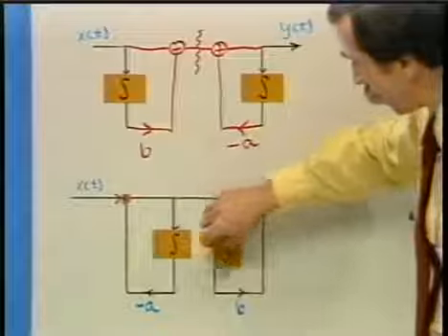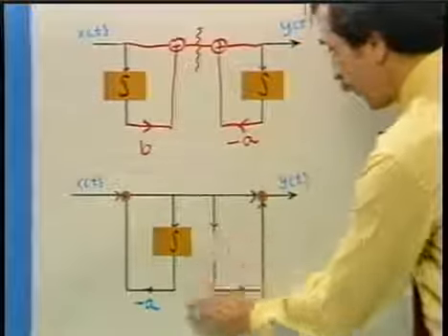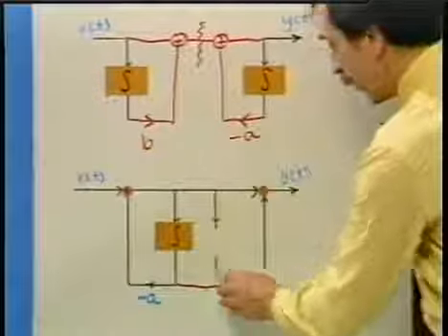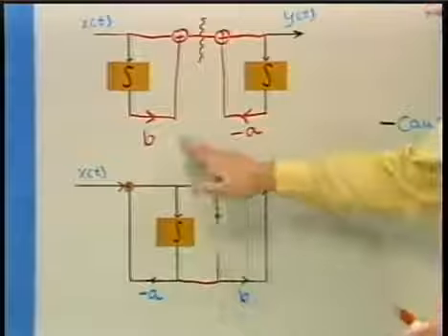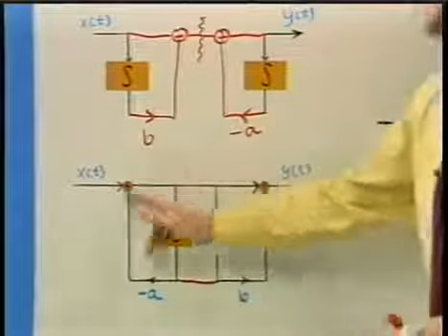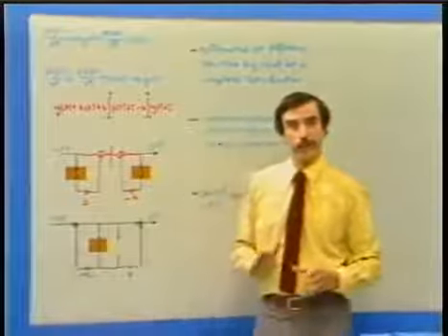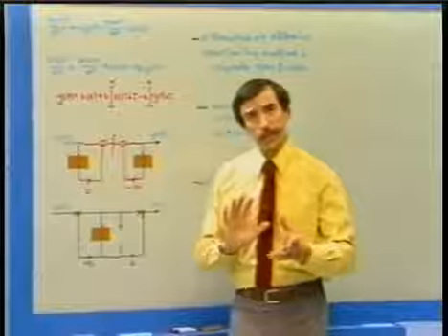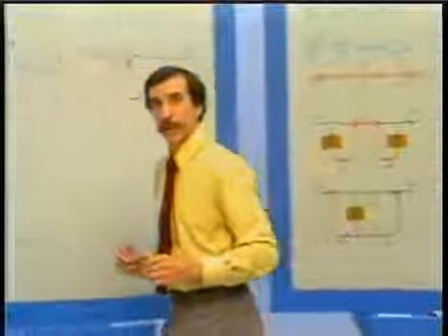We can remove this integrator, break this connection, and tap in at this point. And so what we've done, by interchanging the order in which the systems are cascaded, is reduce the implementation to an implementation with a single integrator. Very much similar to what we talked about in the case of the difference equation.